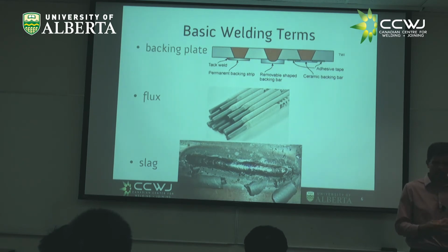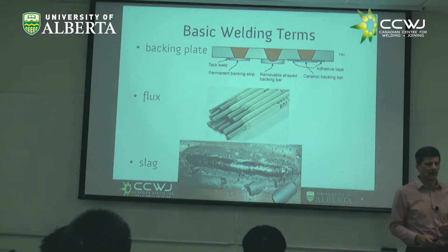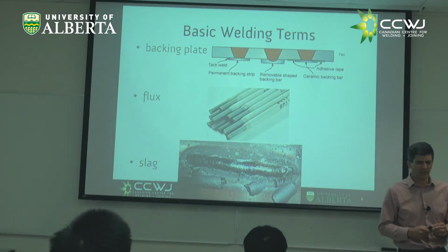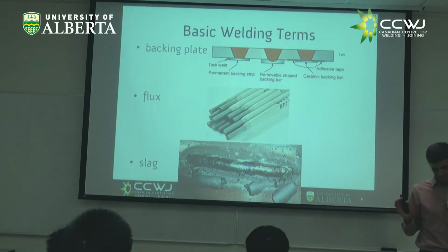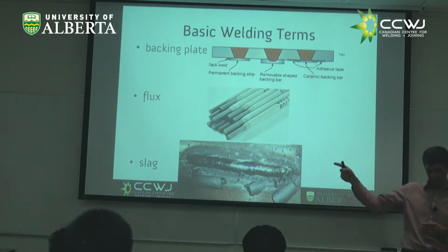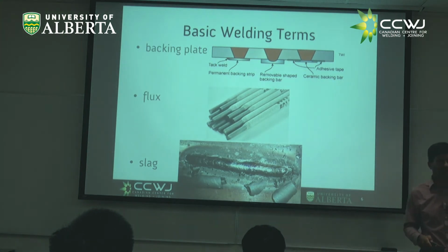The other problem is if you're welding outside. What do you think about using a shielding gas and welding outside? What can happen? It blows away. And then you paid for the argon that went downwind, and you're having all this air causing a reaction in your steel. When steel is not shielded, it looks like Swiss cheese. So it is a problem you very quickly notice.